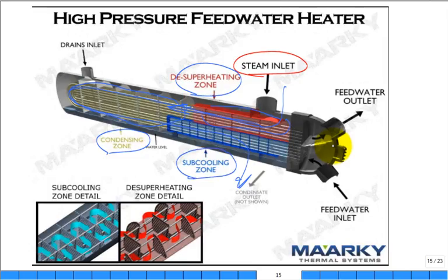And what comes out is liquid from that feed water heater. This is a closed feed water heater. Somebody said, why don't they have a nice illustration of an open feed water heater? It's two pipes, and you put them together. It's mixing, right? Not much in there. But here's a shell and tube. And you can see that they bring in the feed water.